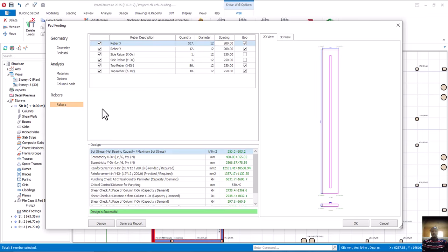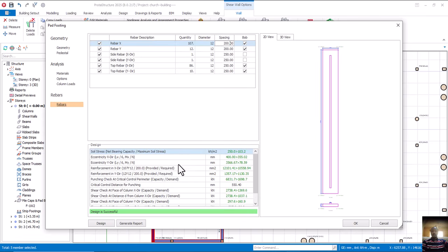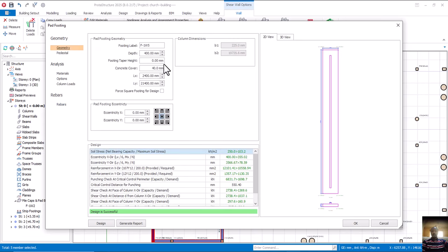But for my foundation, I don't really like using Y12, because even as I'm working at site, I just came back from site, the kind of reinforcement sent to me at site is actually alarming and annoying. That's why I don't like using Y12, because Y12 is as good as Y10. I bet you the Y10 sent to me at site, we are using hand to bend it without any stress. We are not applying too much force, so we are bending this easily by hand. Not to talk of Y12, which is as good as Y10 and what the client is buying.